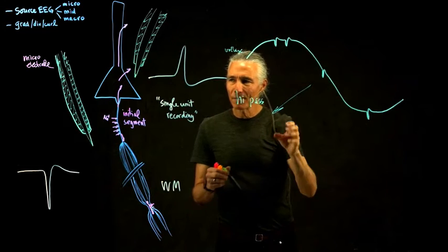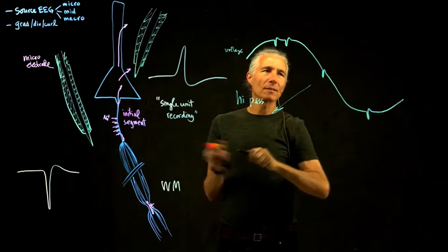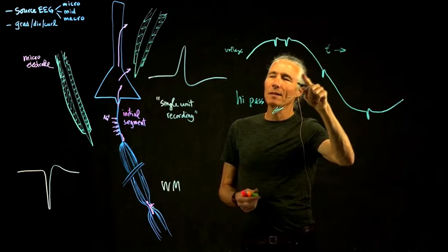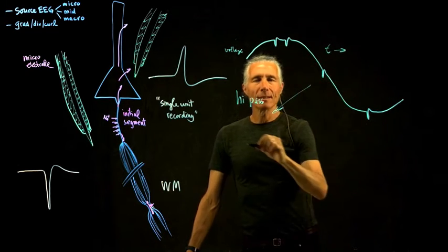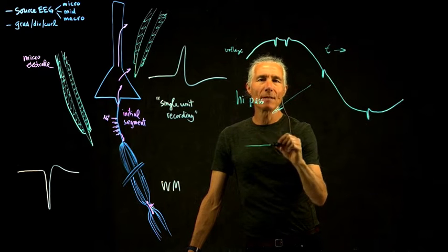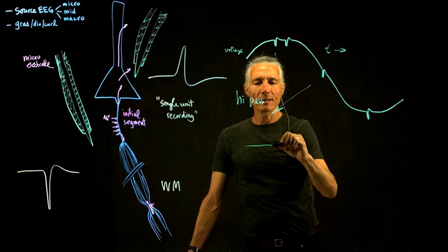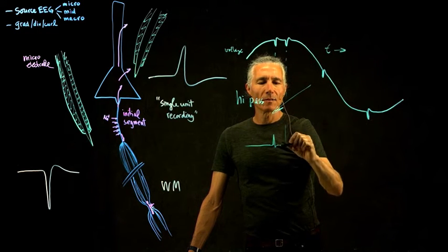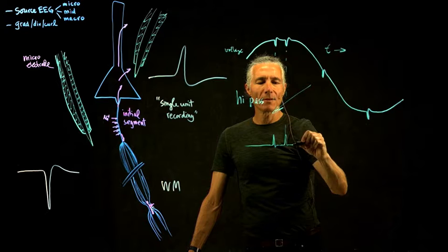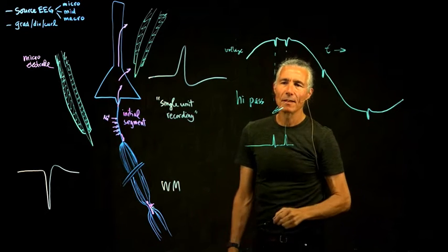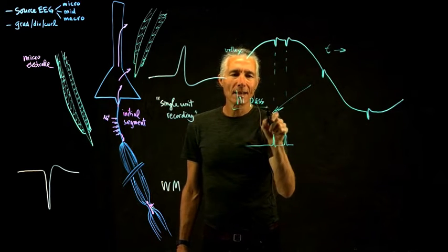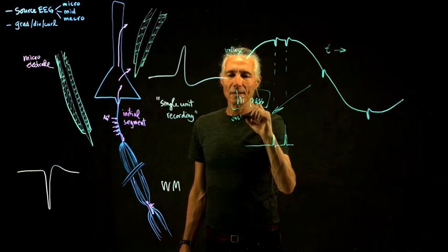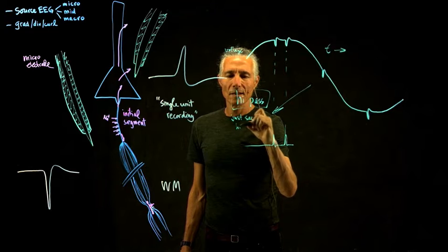So you can do some kind of filter on this time signal. This is time going this way. A time domain filter will essentially get rid of the low frequencies. And in that case, you just see the spikes. Often you might see a paper where they show spikes happening like that against a flat baseline. So that's a high-pass filter. That means just see high frequencies.